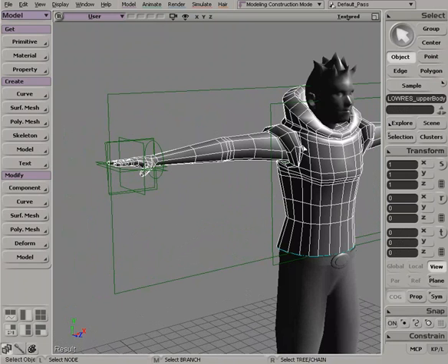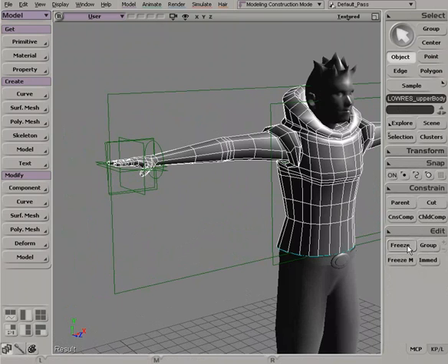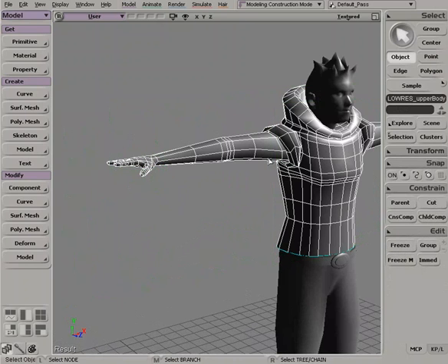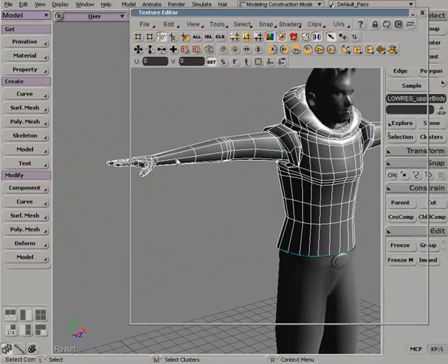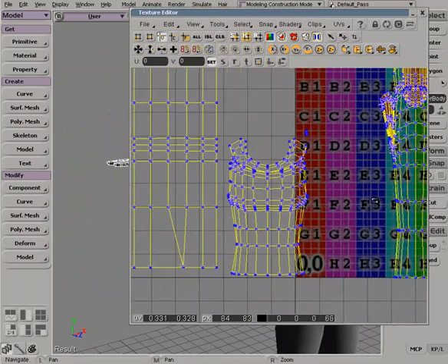object. What you need to do instead is select the object, and then down toward the bottom underneath Edit, you should see the option to freeze your selected operator stack. So if you freeze that, that will now bake these UVs onto your object and remove those texture supports. So there we go.